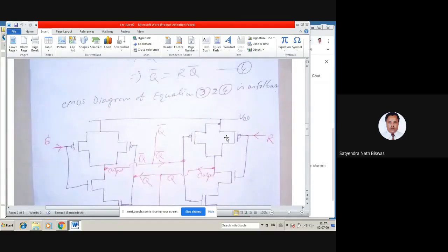In here the 2 PMOSes are in parallel, and 2 NMOSes are in series. So you see here in the 2 gates in the right side, the input will be R. This is the primary input R, and then another input of the 2 gates are connected, and that input will be Q bar, and that Q bar is actually coming from the output of the left circuit, and that was a Q bar as well. So this Q bar and Q bar will be short circuited, and that will be connecting the 2 circuits.